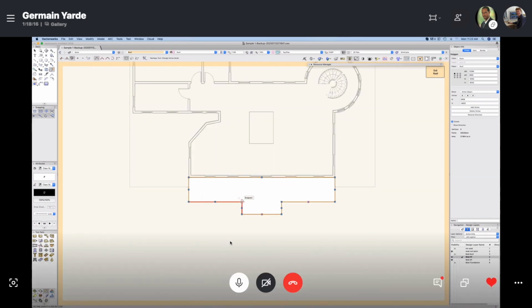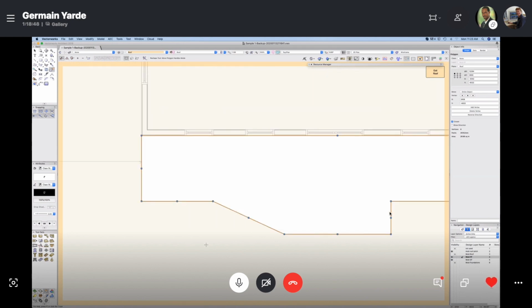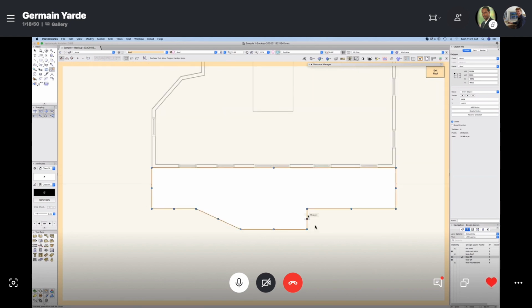Okay. So at the moment, that is a corner vertex. Okay, so if you just click back onto the first mode of the reshape tool, hit U 3 or 4 times. There we go. Now click and drag it sort of 45 degrees to the left. Same on the other side. Okay, that's what we've done. So we've kind of reshaped the roof. Now click exit roof.